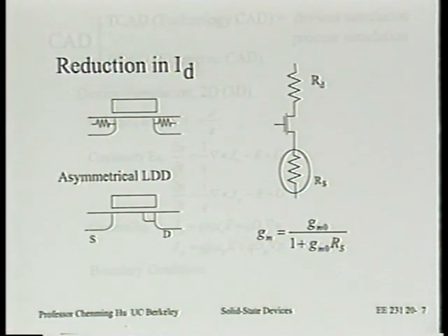So those are all interesting things you can do once we know some modeling skills. And by putting those numbers on, we conclude that, again, this is not tremendously of a problem. We do think that's going to cut down our current by perhaps 10%. And maybe this will creep up a little bit depending on what kind of power supply voltage we need in the future. If we don't need very high power supply, we don't have to try so hard with the LDD to reduce EM, you see that? Then we don't have to hurt so much.